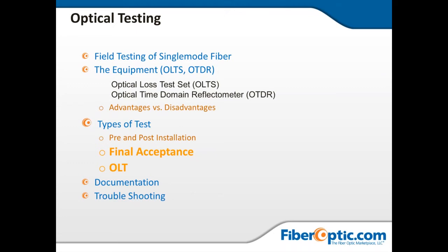Now, if you compare that to what we think of as the much more expensive OTDR, and certainly our best troubleshooting and testing tool, it's because this can see into your cable plant. It can and will draw you a picture and can calculate the loss occurrence at each connector and in each splice. So the key word here is it's a calculation of loss based on all backscatter and reflections, because that's what it's tracking. The back reflections after the laser launch, and it will draw you the graph.